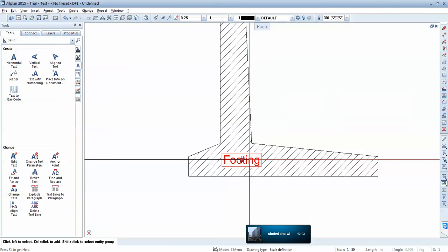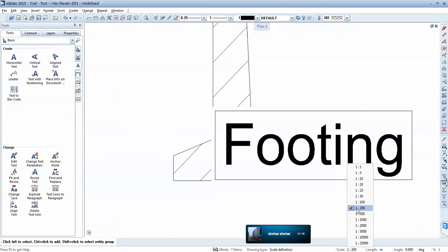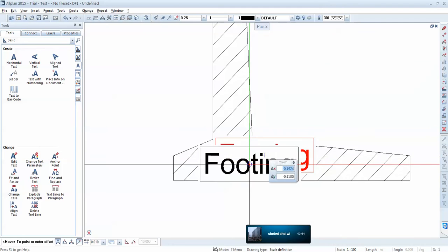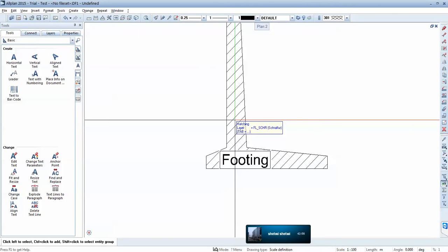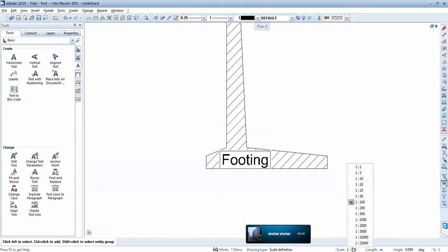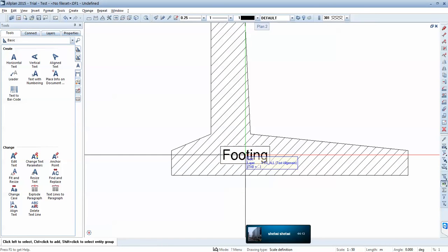And you've seen, if I'm going to draw this one on this scale, 1 to 100, it's really big text, because this is 5 meters long. If I'm doing the scale, I'm going to draw it 100 times smaller than in reality. The drawing will be a few centimeters. So this is normal according to the scale. So actually, by changing the scale, I'm changing the size of the drawing and not the text. However, the illusion is that I'm changing the text size.